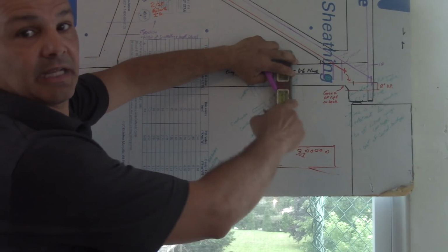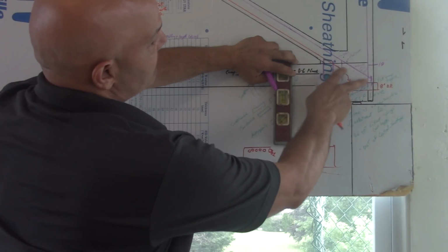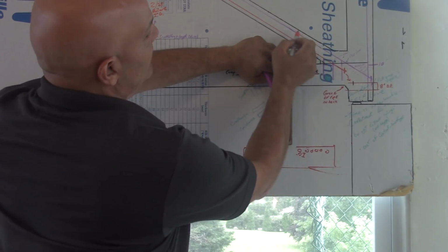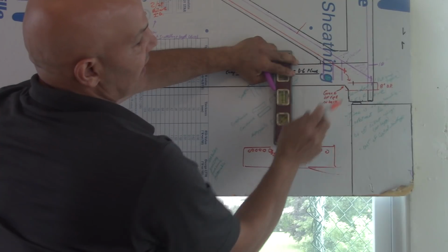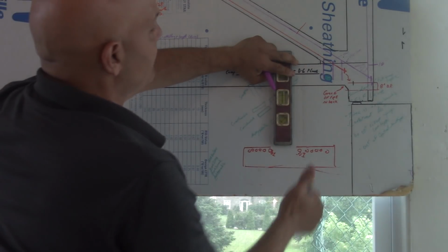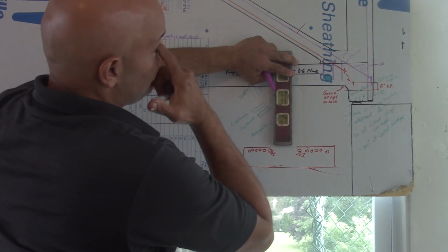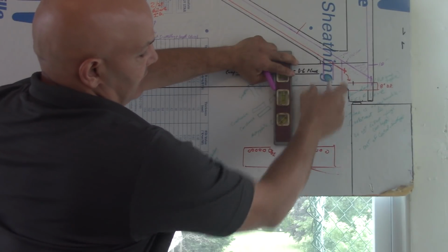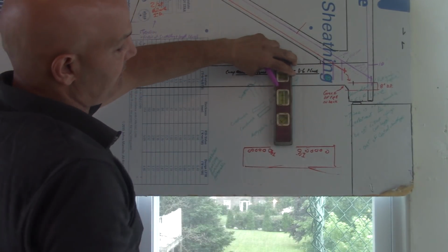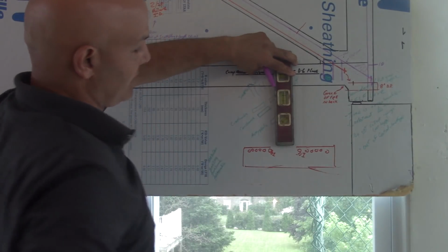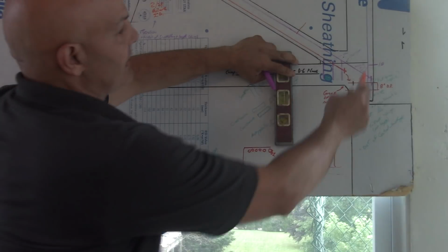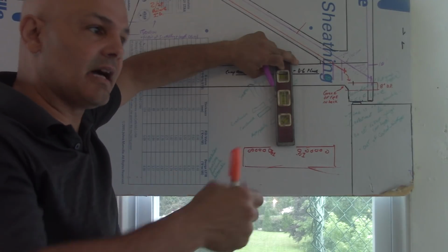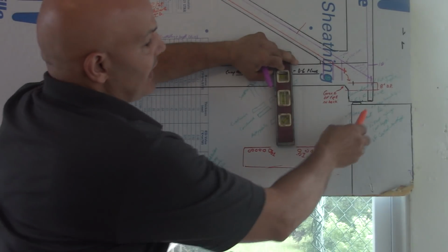When they released the clamping force of the back of this member onto the bridge, that held it on the bridge like that, that was this clamping force down B only. A was inside the deck, so it didn't participate in clamping force. It didn't participate in directly holding 12 onto the deck. When they released that, when they released the clamping force, that little bit of energy that was inside 12, and I say little bit because they detensioned, they didn't undo fully the bar. I think, and they did not grout here.